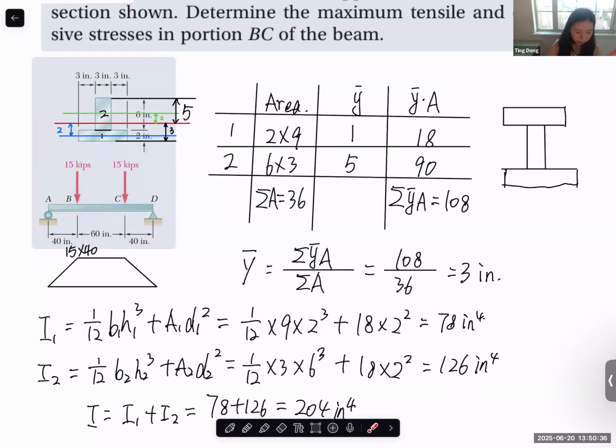You cut through a random point in the BC section, and you do the free body diagram and equilibrium equation. You have the equation of bending moment through the BC section, and you will get a constant value. Now you go through the CD section; of course, you can use the left side or the right side.